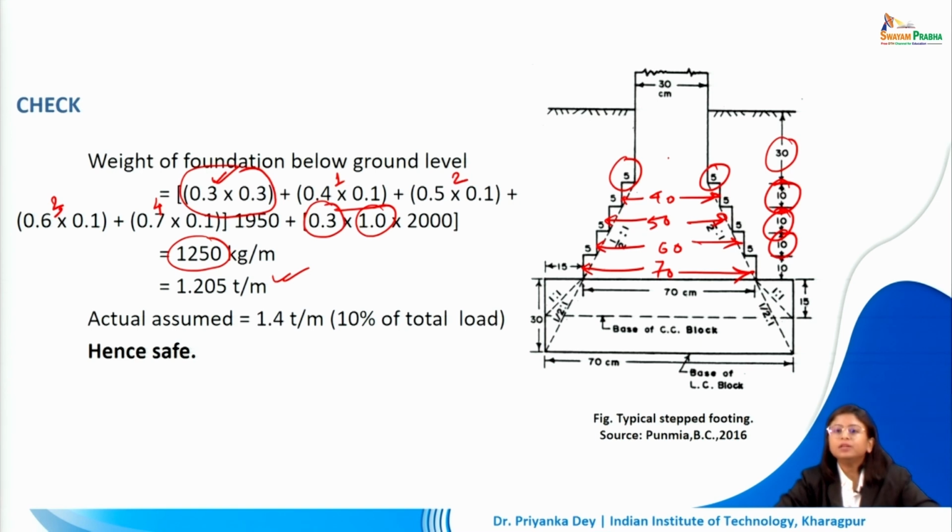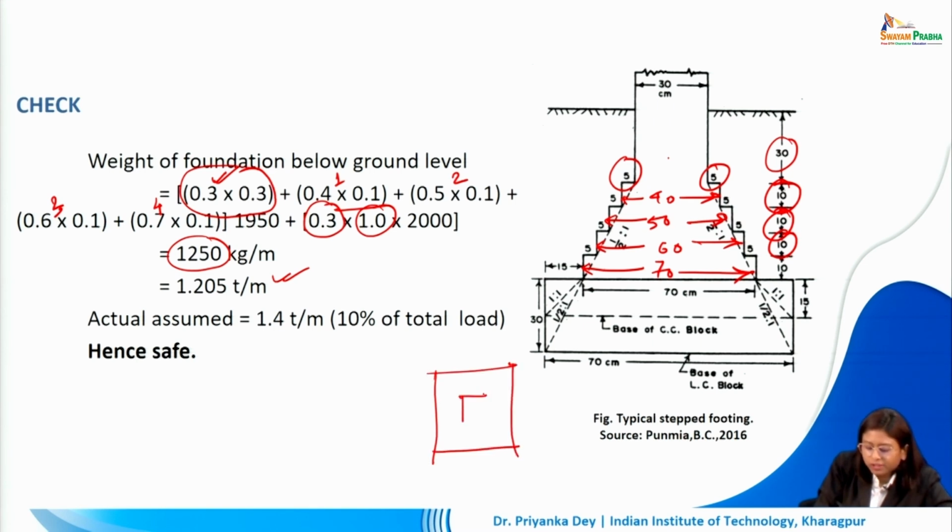Now if we are dealing with a context where we are not going for walls, we are dealing with columns. So for columns we would have to design an isolated pad footing with a concrete base. A similar process will be taken where we will calculate the minimum depth using Rankine's formula, and we will calculate the minimum width, that is capital B, for the base of the footing. In this case, of course, we will have to ensure that the shape of the footing is corresponding to the shape of the column that is resting on it.